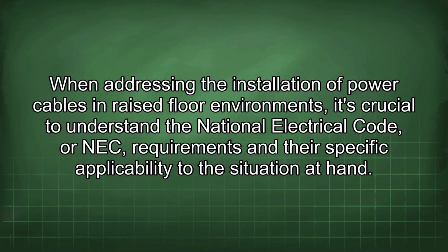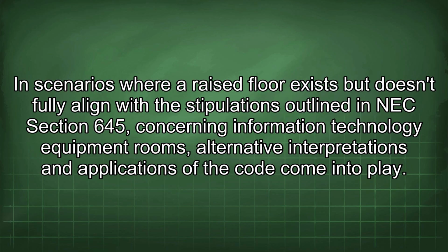When addressing the installation of power cables in raised floor environments, it's crucial to understand the National Electrical Code (NEC) requirements and their specific applicability to the situation at hand. In scenarios where a raised floor exists but doesn't fully align with the stipulations outlined in NEC Section 645 concerning information technology equipment rooms, alternative interpretations and applications of the code come into play.